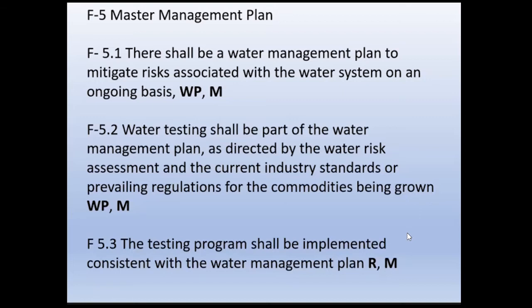So your water management plan is going to include your preventative controls, your monitoring and verification, your corrective actions and the documentation, and then think about your crop stage, the application of your irrigation water, the timing. Those should be included in your water management plan, because through method of application and timing of application, your risk may actually be fairly low. Again, anytime that a change occurs in your water distribution system, or you go to an alternative water source, your management plan needs to reflect that change.